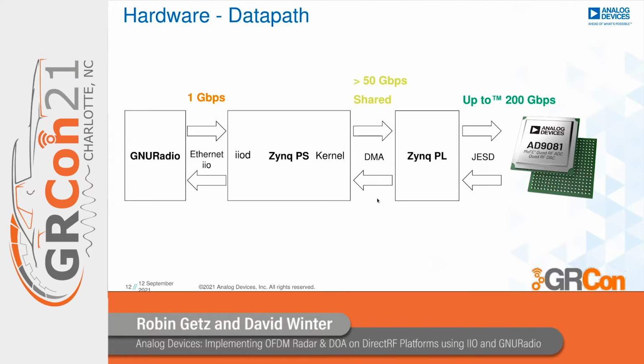The other stages in the data pipeline can carry more than enough data, so the DMA, for example, is probably limited by access to the main system memory, and there we can expect to get like 10 gigabyte per second of throughput, which should be enough. Also, our JESD lanes obviously aren't fully used at around 40 gigabit per second with 8b/10b coding overhead.